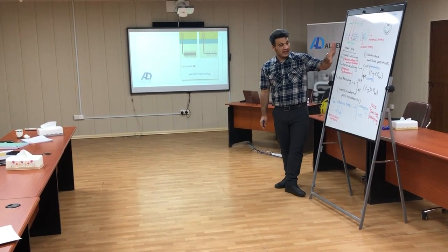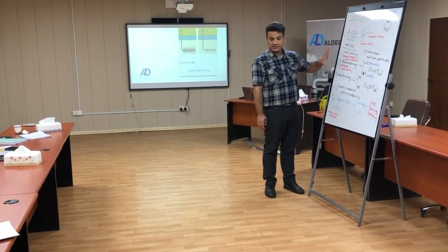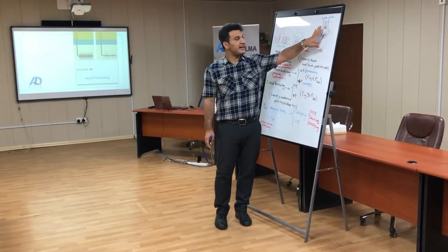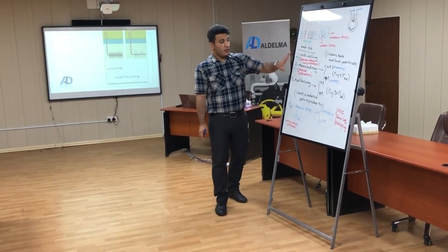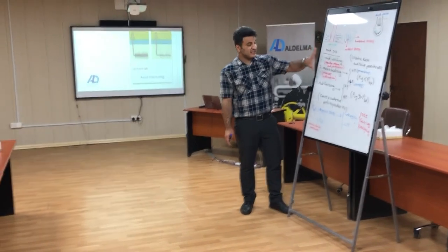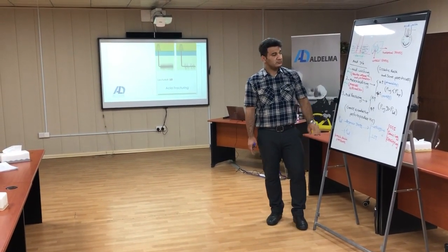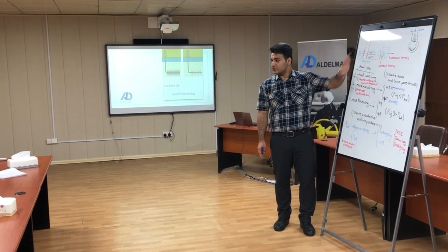So, a brief about the acid operation jobs. First, acid washing just removes debris and cuttings at the wellbore. For matrix acidizing, we just inject the acid with a pressure less than the breakdown pressure to create wormholes and react with the reservoir rock.